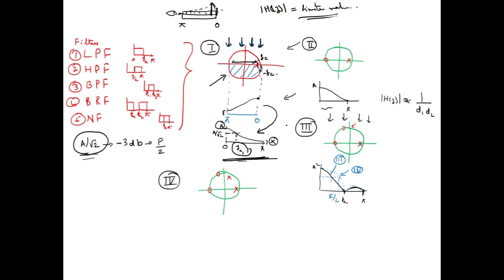Now, as I told you, in many cases this residual amplitude at pi radians is not recommended. Okay, why is it not recommended? It is not recommended because having some gain at pi radians means at the Fm value some signal components will be passed.